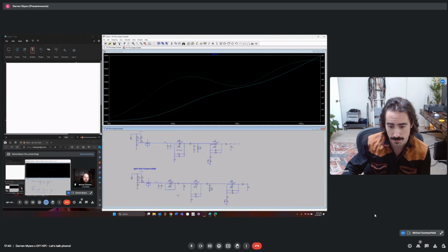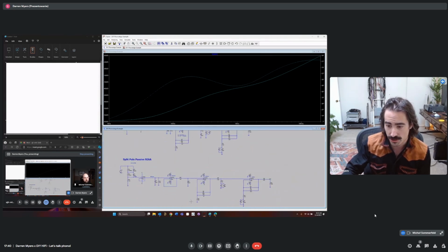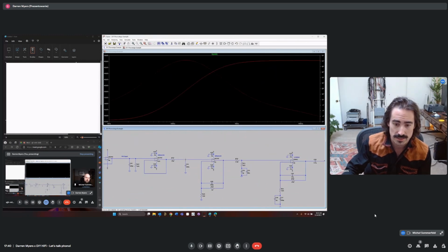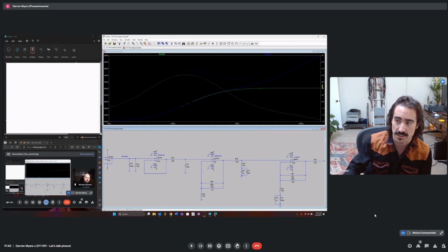We're going to be applying it much earlier so that there has been no gain applied to the system, but we're applying that time constant, and you can see right there, we shelf it down and we've applied our 75 microsecond time constant before we've applied any gain.